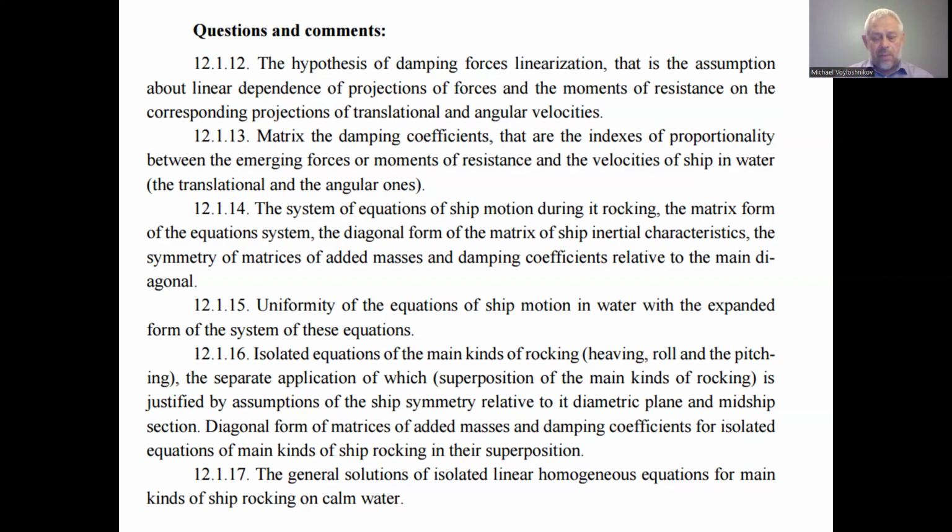So each row of the matrix of added masses or damping coefficients means the factors to determine the forces arising in one definite direction. It could be one of six directions in the Cartesian system of coordinates: three translational and three rotational.